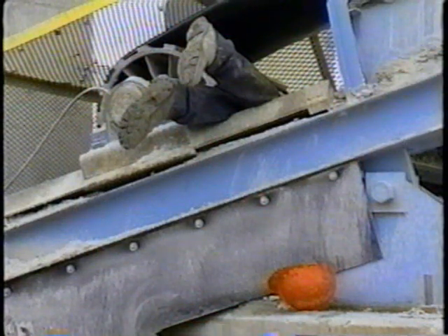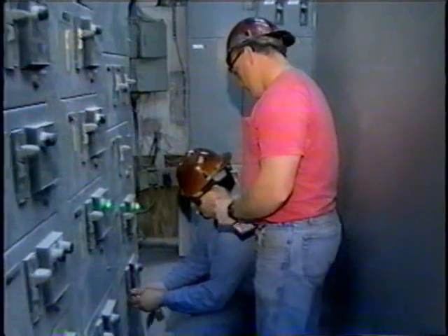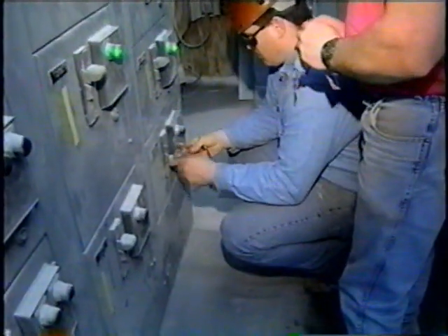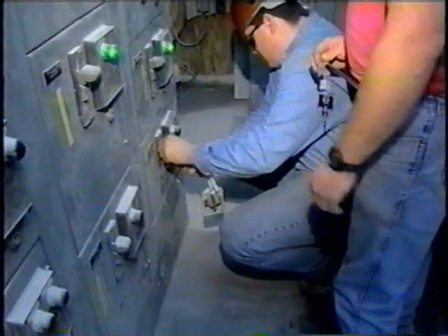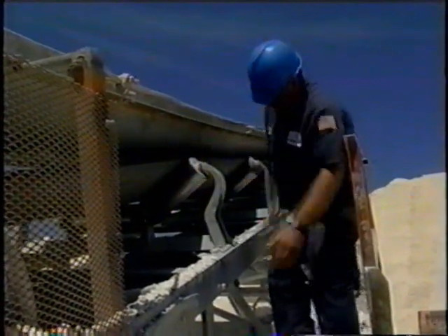Conveyors have tragically claimed both life and limb from miners working unsafely in this area. First of all, energy sources should be locked out, tagged out, and tested to be non-operational before guards are removed and/or inspection or repair takes place.